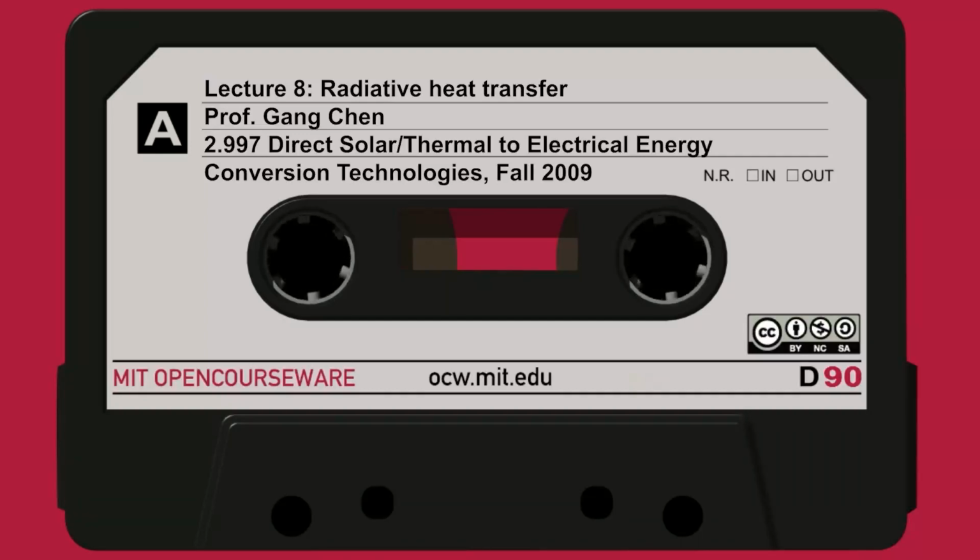But also the panel itself is tilted at an angle of 37. So it's not a perpendicular incidence from the sun to the solar panel. Right here is 37, so the angle of incidence is 11.2 degrees. People typically use 1.5G for solar cells.